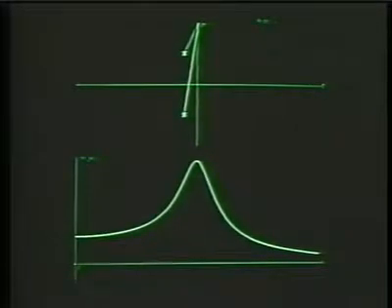And so, in fact, to illustrate that further and dramatize it as long as we're focused on it, let's now look at the frequency response for this second-order example as we change the pole positions. First we'll let the poles move vertically parallel to the j omega axis and see how the frequency response changes.